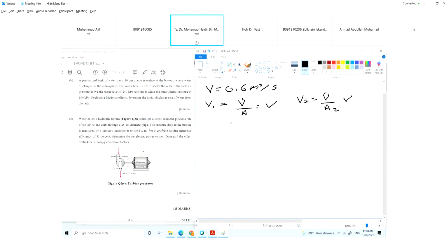The second is, you know the pressure difference, delta P, which is equal to a pressure drop. If it is a pressure drop, it is P2 minus P1, equal to 1.2 meter Hg, or rho G H, where rho density is 13,600, G is 9.81, and H is 1.2. Now you got the pressure difference in Pascal. Then you can directly use the power equation.